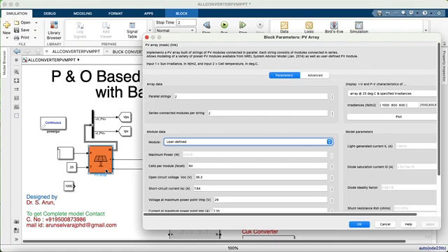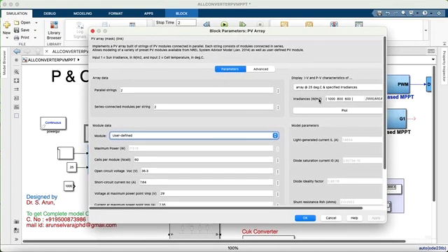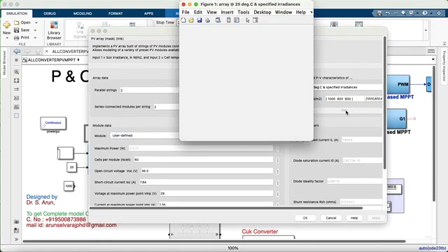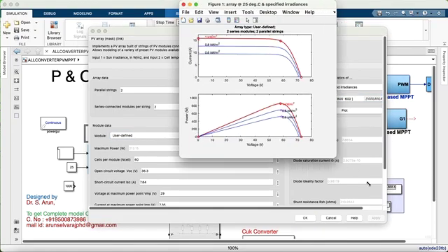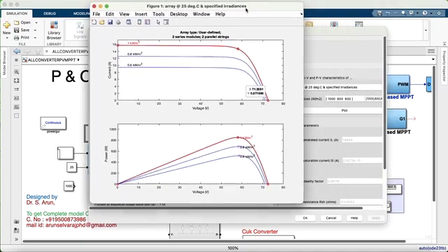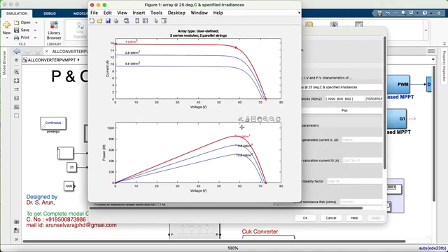So here I have created a 1 kilowatt solar panel. It is a user defined function. I have mentioned different irradiance levels to extract the maximum power. So I have created 1000, 800 and 600 irradiance levels. These are the PV characteristics for the different irradiance levels. For the 1000 irradiance level, it reaches nearly 852.6 watts at the voltage of 58. This one is the 1000 irradiance level.